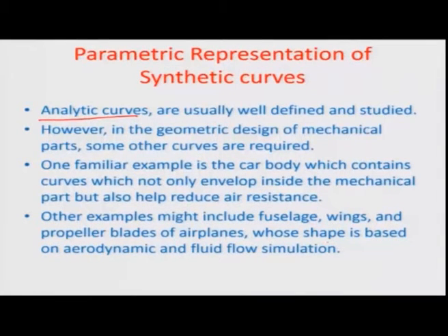Here we will talk about synthetic curves. Analytic curves, as you have seen earlier, are usually very well defined in terms of the functional relationship as well as the symmetry which exists in terms of the parameter which is taken, so the definition, whether it is parametric or non-parametric representation, is quite simple. However, in the geometric design of mechanical parts, there can be an extremely complex contour which may be plotted by a bunch of different curves rather than these standard analytic curves.